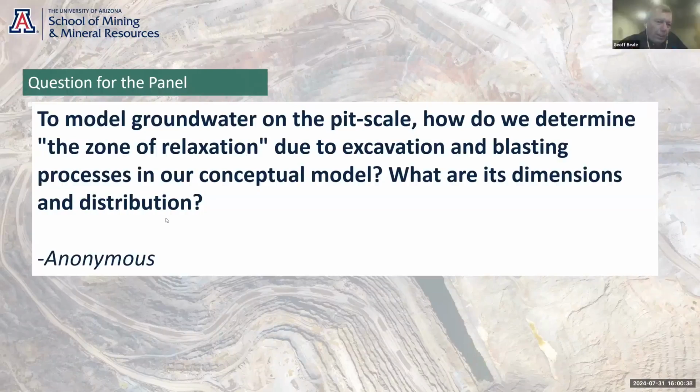Okay, I'm going to say the best way of doing it is to look at the piezometers. Quite often, the dilation of fractures, particularly when you get more than about 50 meters behind the slope, is very, very small. And it's very difficult to pick any mechanical differences up in drilling, although there's lots of people tried it.